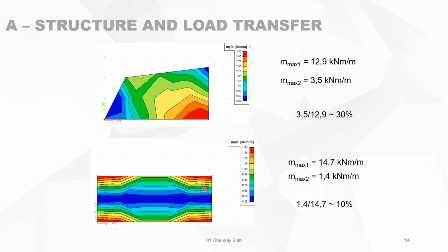Now, in principle, the bending moment in the y direction is zero in this slab. But this finite element program shows some bending moment in this direction due to the program itself, due to the finite elements.